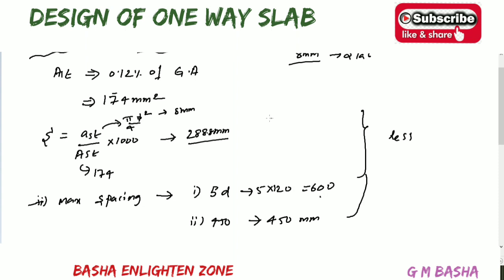What IS is saying is, simplify these three, and whatever is less you can provide that much. But for example, if you get a spacing value of some 650, according to these conditions your maximum spacing does not exceed 600 and 450. Whichever is less means 450. So even though your value will be 650, you can't go beyond 450. Even though you get 650 mm spacing allowed, you can keep the spacing as 450 mm according to our IS.